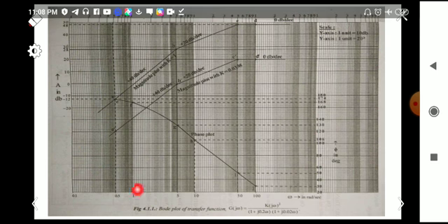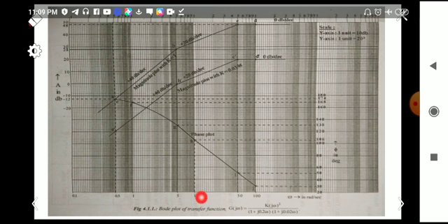When the next one comes here, in the semi-log graph sheet you can see 1, 2, 3, 4, 5, 6 up to 9, and again 1 2 3 4 up to 9, like that. Each time a 1 comes, it means the frequency is multiplying by 10. So the first frequency we are choosing is 0.1, for the next one it will become 0.1 into 10, that is 1 radian per second, then 10 radian per second, and then 100 radian per second. Like that we have to mark.